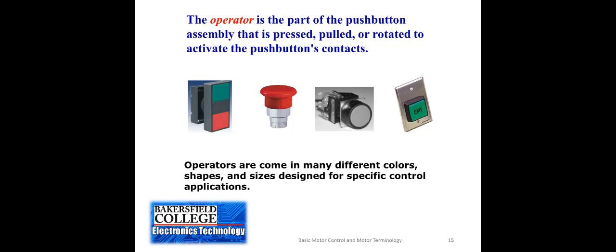Here's some of the different types of operators that we can have. We can have one that is stacking a start-stop push button in the same operator, and then you would have one contact block that would be activated when you push that green button, and then you'd have a different contact block that would operate when you push that red button. The one next to it is a mushroomed head, and remember, we use those as a quick, fast way of having the operator just slam his or her palm into it, and that will activate the switch.